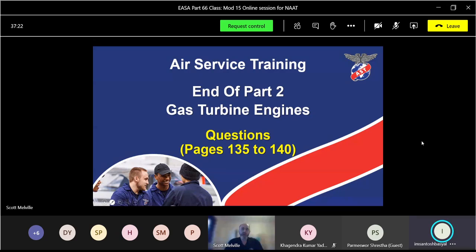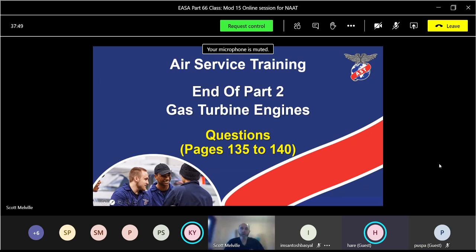What is the purpose of the LP cock? Isolate. Isolate, yeah. So when can we use it? On ground engineers. Say again, sorry? During maintenance. During maintenance. And what else? So we can isolate for maintenance. Emergency, yeah? In emergency cases.